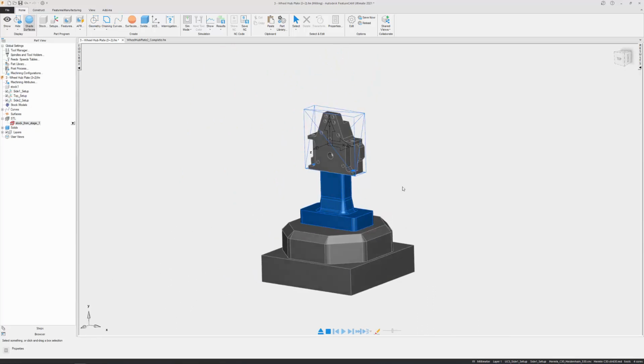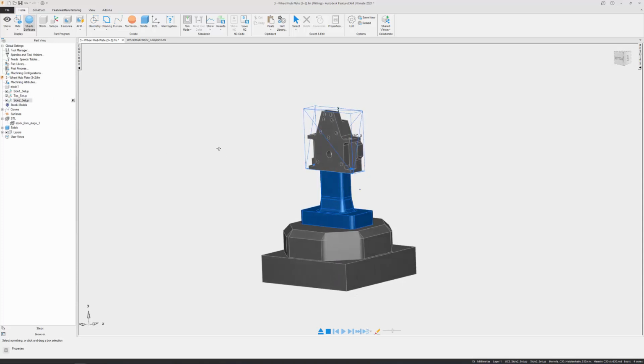So now for the programming of this 5-axis positional or 3+2 part. You'll notice that we have multiple setups here. Each one of these is necessary in a 3+2 part to essentially define the tool axis for a given feature. So in this case, we'd really just have 3 setups. Everything we do from the side setup, then what we're referencing is the top from this orientation, and then that back setup.